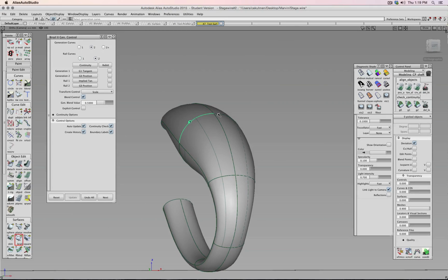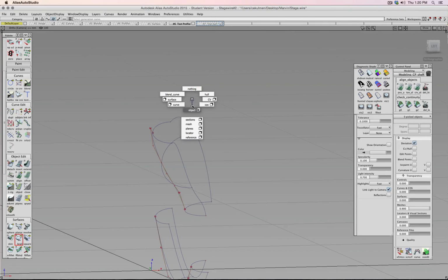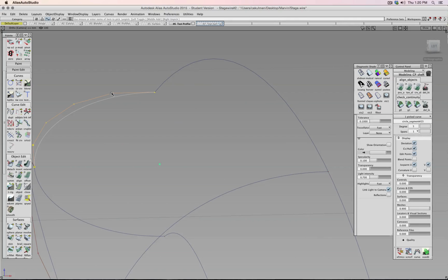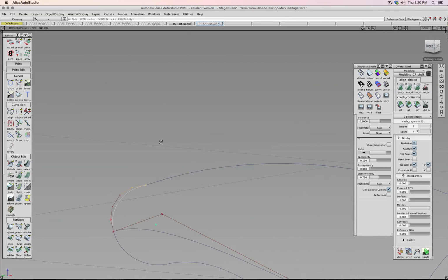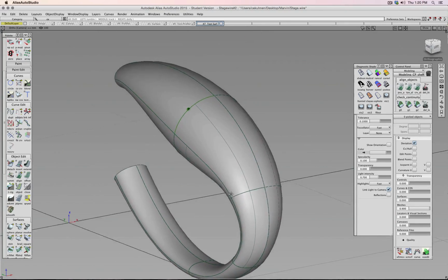the circles I created when I split them, for example, let's hold on one second. Let's select this curve, turn on the CV. You see there's just one CV, kind of like doing the tangency. So this is actually positional, not positional, G1, which is why now for the surface I can't say, hey, do this G2, because my input curves weren't really set that way.